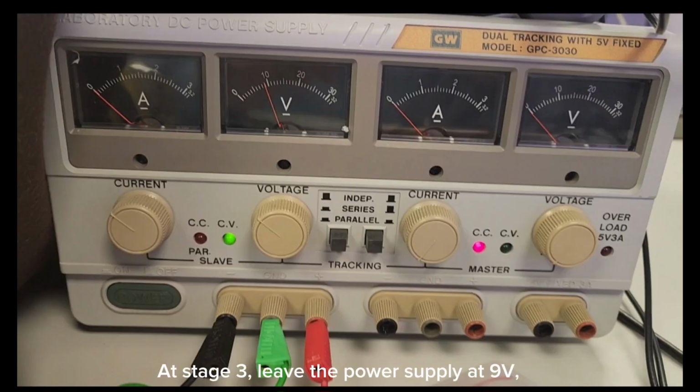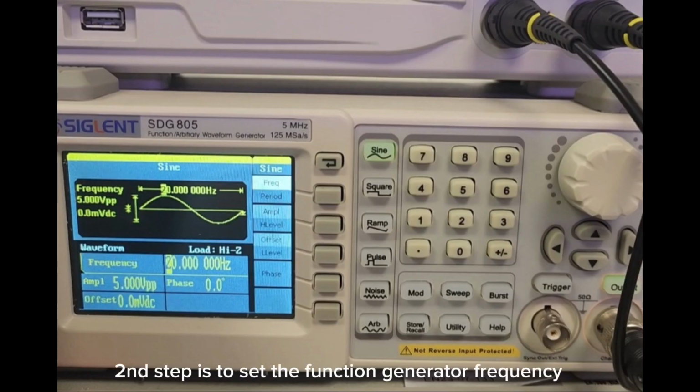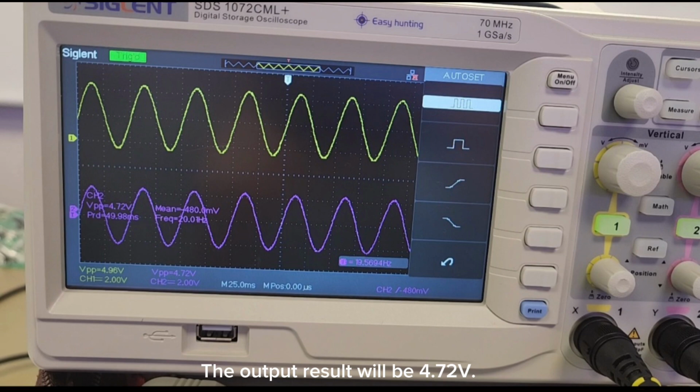The bandwidth will be 950 Hz, which is quite near the cutoff frequency that was calculated just now. At stage 3, leave the power supply at 9 volts and set the clips from the power supply to the circuit without connecting the green clip. Second step is to set the function generator frequency to sine wave at 20 Hz, 5 volts peak to peak. The output result will be 4.72 volts.